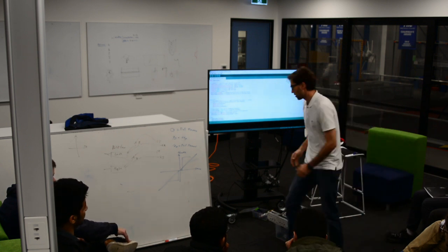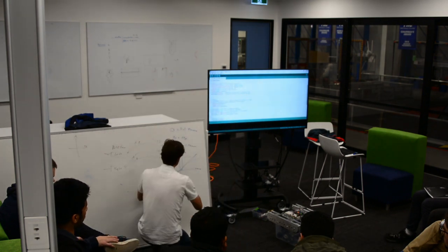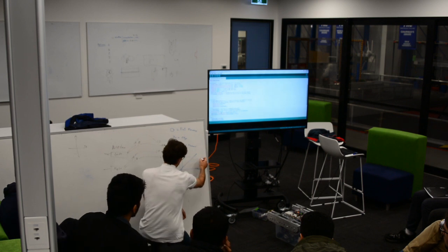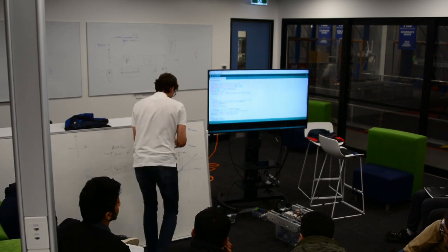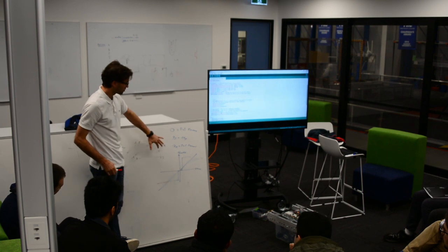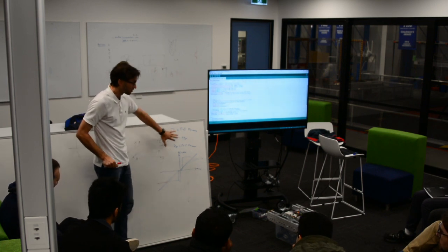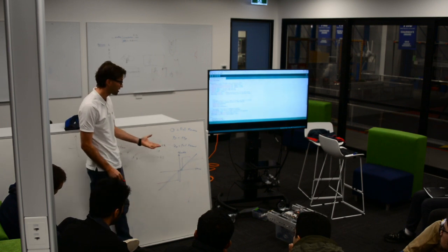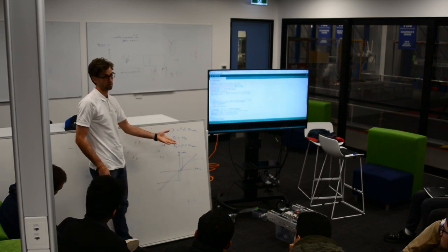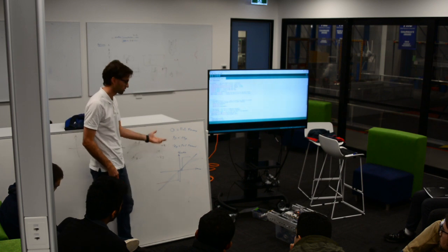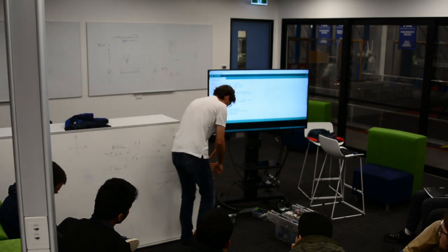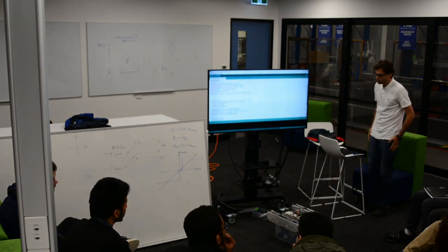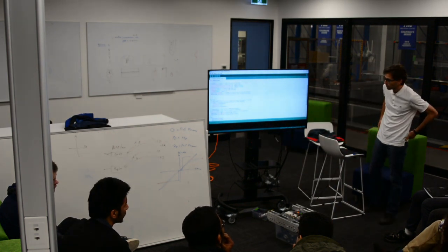So does that mean that it's basically a bang-bang controller until it gets to a... Yeah, that's right. And there is a limit to the throttle that you get here. And so one of the things that happens when you're doing anything in real life, so that's really what you've got there, right? Your throttle is limited. So if you took your principles from 324, you generally assume lots of linearities, and this is suddenly a non-linearity that can annoy you. And there are also non-linearities like the total amount of current you can draw from this, the total voltage you can draw from this. There's all sorts of non-linearities that may put limits on it, but that's absolutely right.